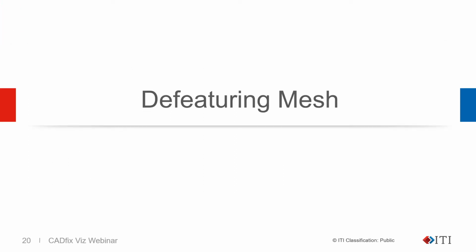And then obviously, once we've repaired our models, we have to generate the mesh. So we have accurate, high quality, watertight mesh generation capabilities. We always produce the minimum number of triangles to capture the geometry within defined tolerances. And this in turn creates models of the minimal file size, which is key. We have full user control over the accuracy settings, so our sag and turn values.